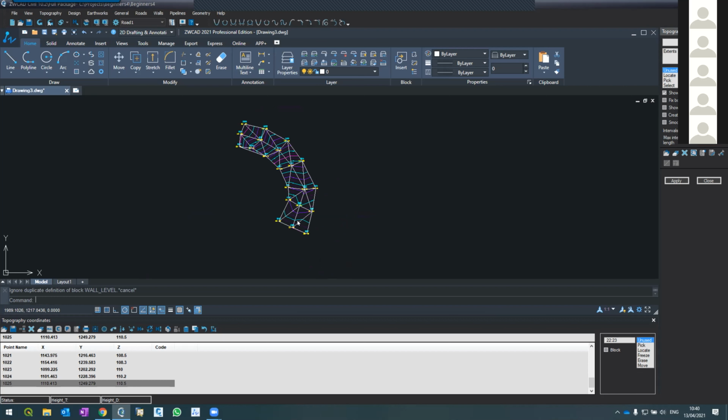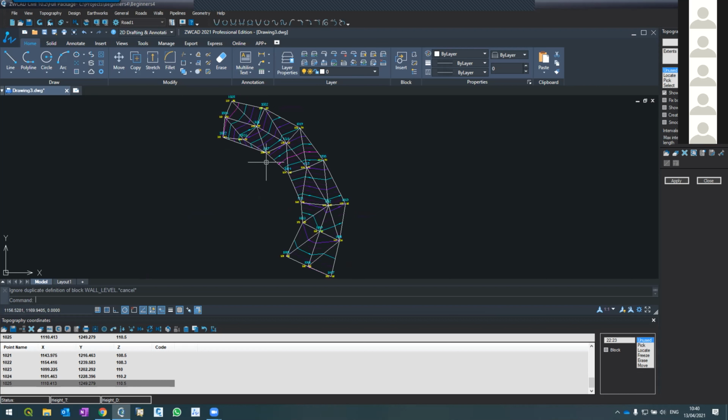Each triangle which is longer than a specific length is removed, this is what we do. Okay. Questions about what I just explained? Any questions? So again, the problem is what we call the border problem. The software creates triangles with edges which are longer than what we want. The solution is the maximum interpolation length: enter a value, press apply and see the result.